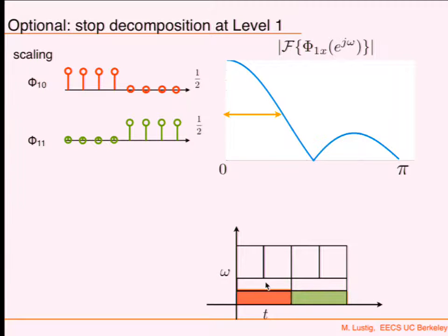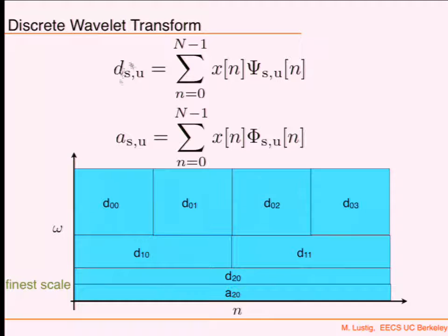And so then I get a decomposition where you have a wavelet here and another one here, which are located at those places. And they're a little bit wider, of course. Wider because they're thicker in frequency, but not narrower in time. Okay? So yes, frequency tiling. That's effectively how it's done. That corresponds then to the detail coefficients and the approximation coefficients, and these would be the decompositions of these.